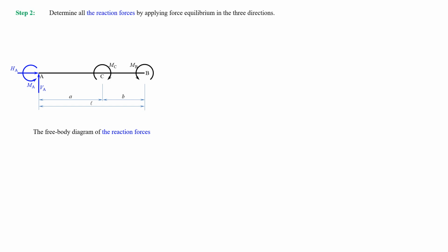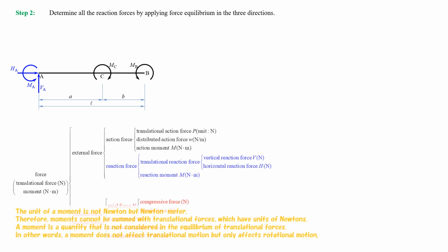Step 2. Determine all the reaction forces by applying force equilibrium in the three directions. The unit of a moment is not newton, but newton meter.